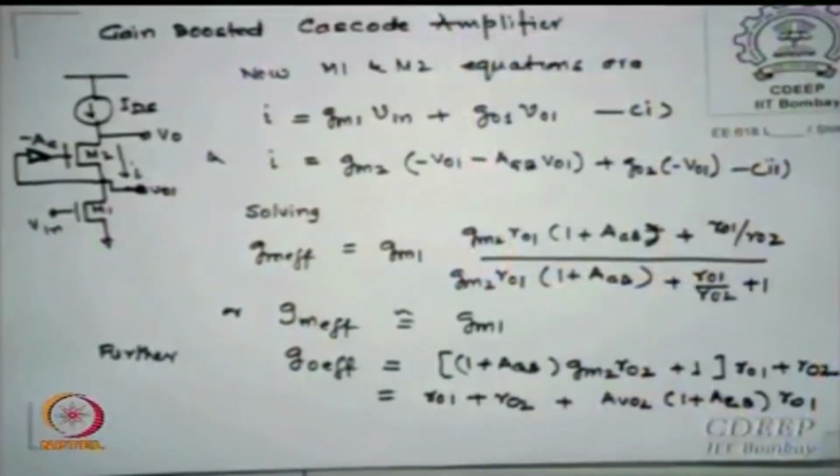What is it that it makes? This is a good current source I put there. But this current source cannot be created out of nothing. So it could have a p channel device, it could have an n channel device, it could have a series of 2 devices even there, whose output resistance will also be there. Is that clear to you? The issue is now what? I assume this is an ideal current source, so I am taking its RO as infinite, but in real life this may not be infinite. Where will that resistance hit you then?